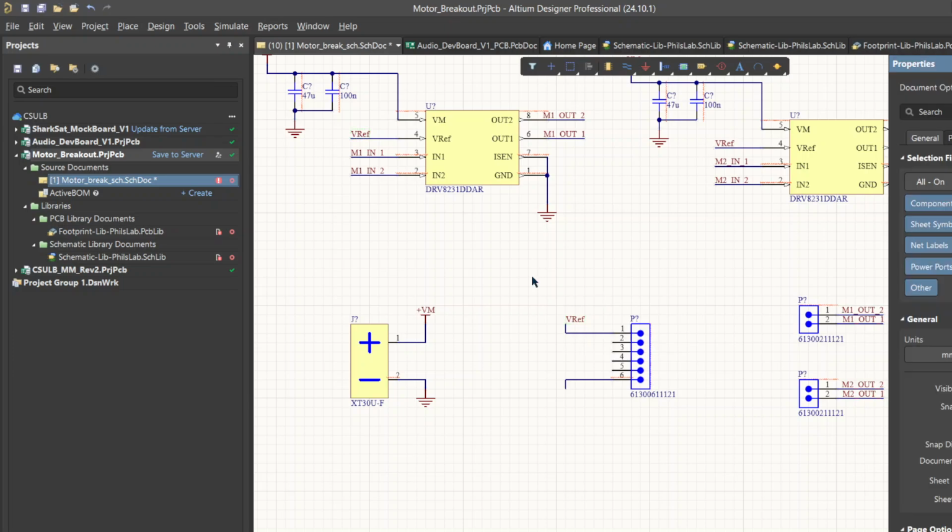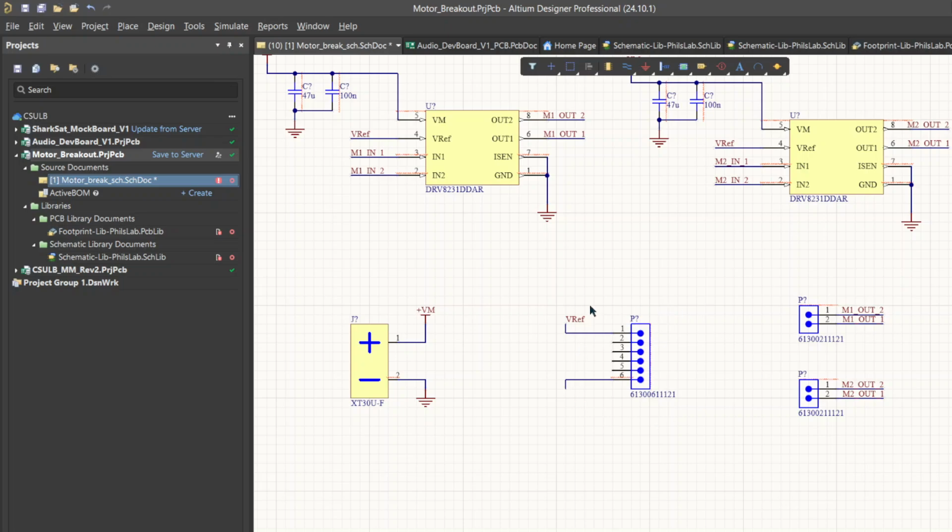There are some things to take into consideration when you're doing these, and you can always Google what's the best format. For example, if you have something that's more sensitive or has a lot of power, you can Google and look around to see which order makes the most sense. For things that are sensitive, it's a good idea to surround them with grounds. But for our purposes, it doesn't really matter.